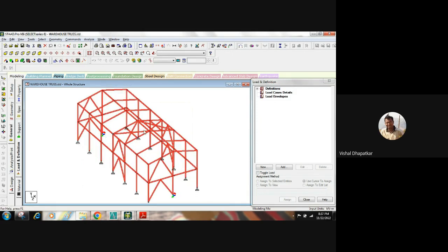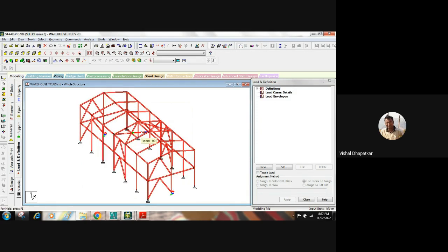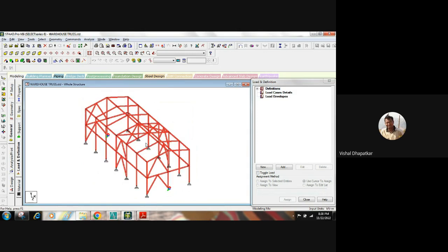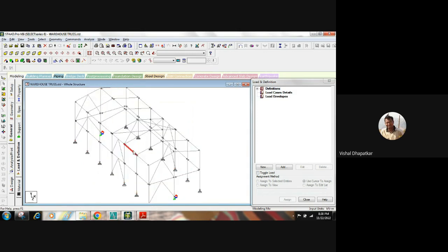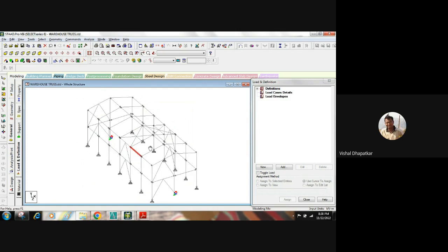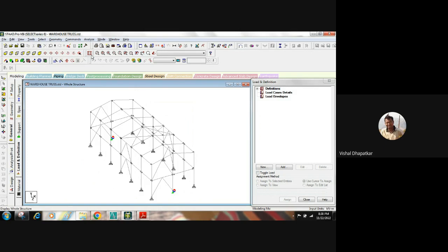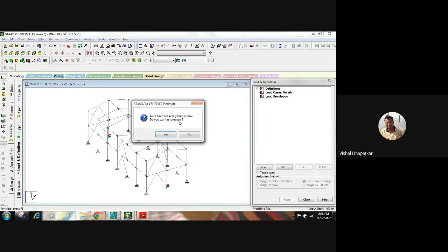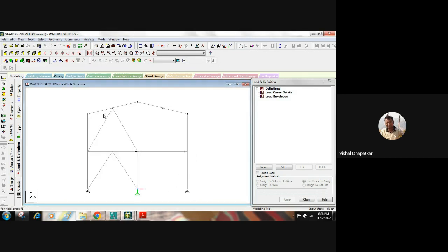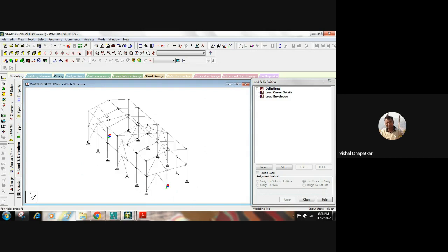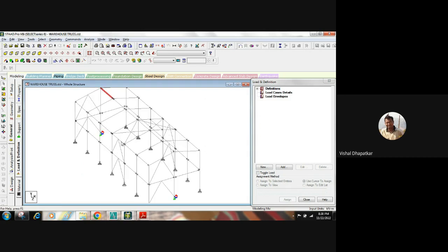इसमें STAAD में बहुत कुछ नहीं है, आपको मेनली ये लोड एप्लीकेशन करना है और ये ज्यादा डिफिकल्ट नहीं है। सबसे इम्पोर्टेंट STAAD में होता है कि आपका पैरामीटर असाइन करना, कि आपका मेंबर का LY क्या है, LZ क्या है, उसका अनसपोर्टेड लेंथ क्या है। तो दैट इज द मोस्ट इम्पोर्टेंट थिंग इन STAAD। तो उस पे ही पूरा सेक्शन का डिजाइन होता है कि आप मेंबर का लेंथ क्या कंसीडर कर रहे हो, because once you create a node, STAAD will not understand whether it is one member or two member.